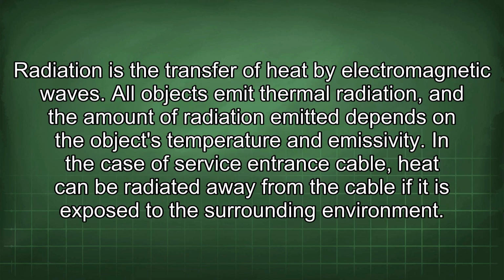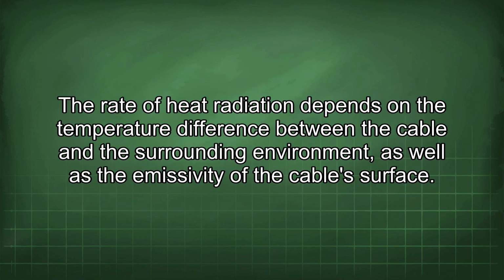Radiation is the transfer of heat by electromagnetic waves. All objects emit thermal radiation, and the amount of radiation emitted depends on the object's temperature and emissivity. In the case of service entrance cable, heat can be radiated away from the cable if it is exposed to the surrounding environment. The rate of heat radiation depends on the temperature difference between the cable and the surrounding environment, as well as the emissivity of the cable's surface.